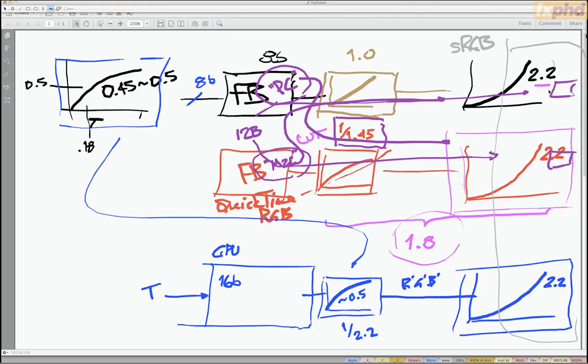And basically, the 2.2 power is suitable when you're going out into a rather bright display, let's say 320 candelas per meter squared, and a rather bright ambient environment like the lights are on. You're not in a grading suite, you're not in a cinema. So the 2.2 number is suitable for those purposes.